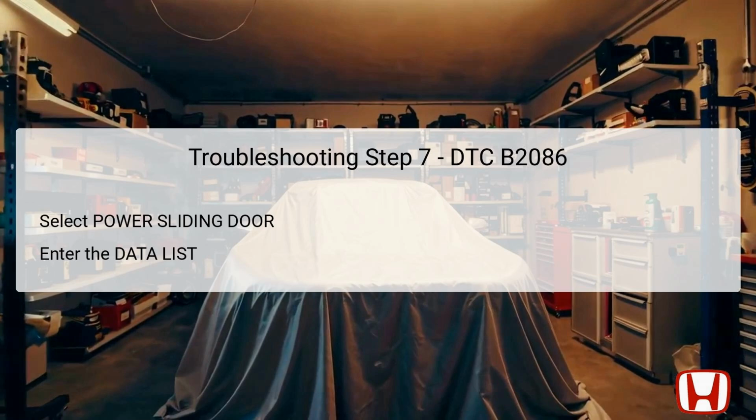The data list provides valuable information regarding the state of various components, including the right power sliding door full latch switch. Observing this data can aid in verifying whether the components operate within the expected parameters. Accessing this information is crucial for pinpointing the specific issue causing the B2086 code to appear. Properly interpreting the data collected can lead to more informed decision-making regarding repairs.